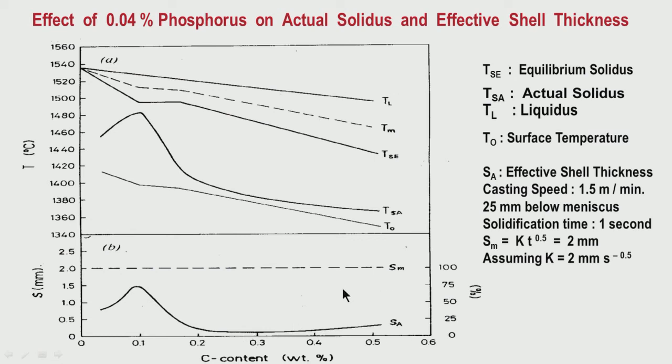Different levels of carbon basically indicate different solidification modes that I have explained earlier in the last discussion. So all these are related. How are the alloying elements controlling the solidification mode? They are controlling it by controlling the carbon equivalent. In plain carbon steel, that means steels which have just carbon, the iron carbon diagram is the criterion.